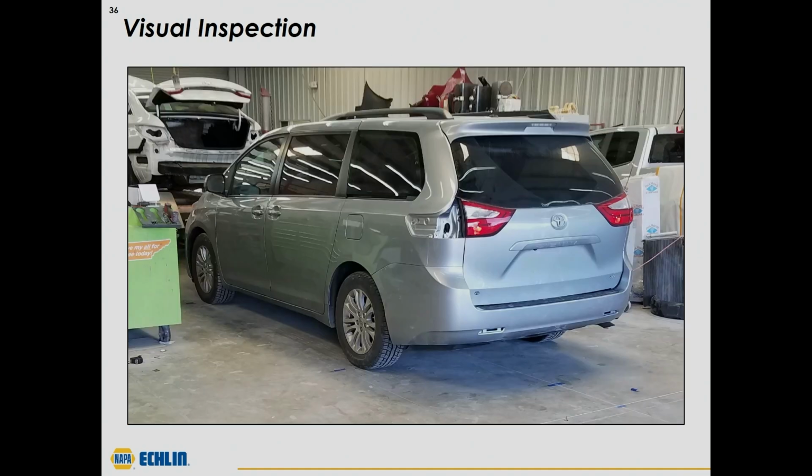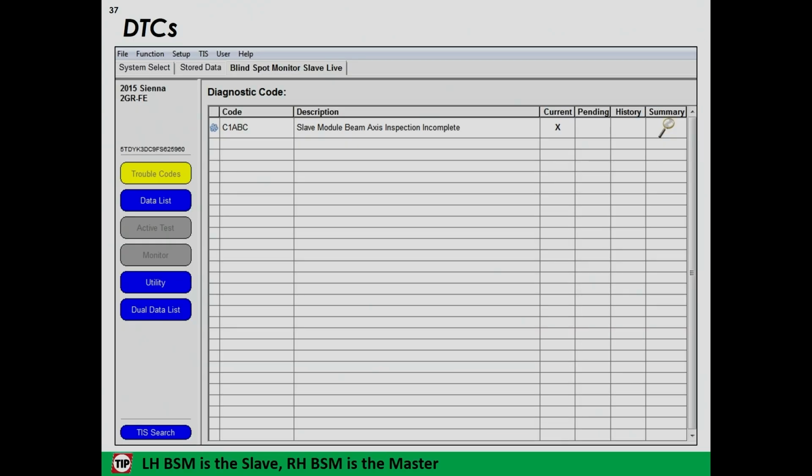So the technician begins by just performing a visual inspection. This came from a collision shop, and they put the rear tail light assembly back in. Looks like it was a good repair from what we can tell. So we're going to keep rolling with diagnosis. And now we do a scan of the system, and we come upon a slave module beam axis inspection incomplete.